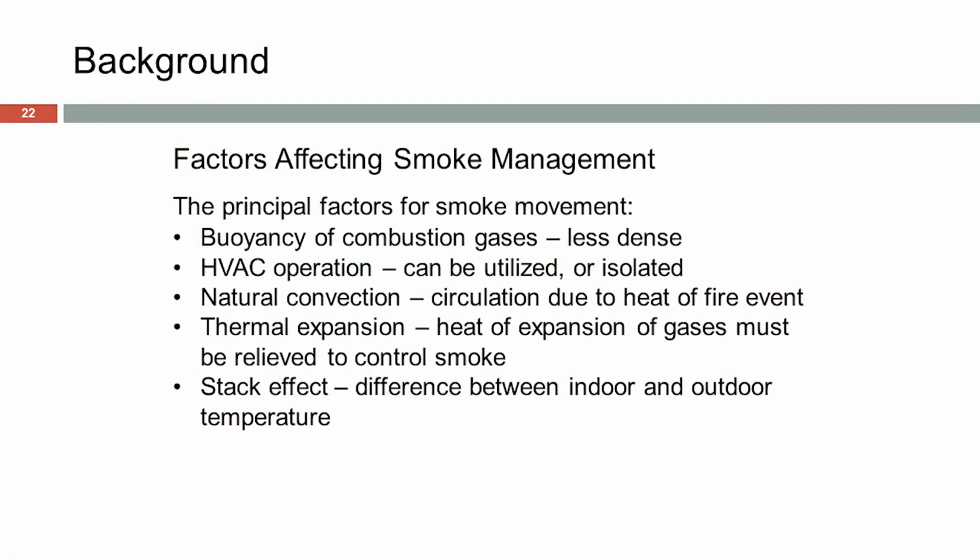So, some of the factors affecting smoke management. When we look at a room like this, right, we got a high ceiling, it's nice, it's airy, it's easy to get comfortable with a lot of people in here because the reserve capacity is built into all this air. Well, some of that is a very strong factor in the design of smoke control systems too in large area environments, malls, atriums, things like that. Some of the factors are the buoyancy of the combustion gases. It's less dense, tends to rise, right?